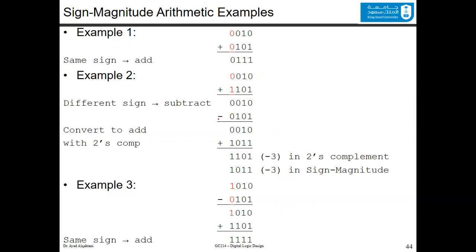So now you do the subtraction. To do the subtraction, this number is the same, and for this number, we know that one way to do the subtraction quickly is to convert the subtraction to addition, and you get the 2's complement of this number. The 2's complement of this number is 1. You keep the first one, and then you start flipping the rest of the bits here. And now you do the addition.